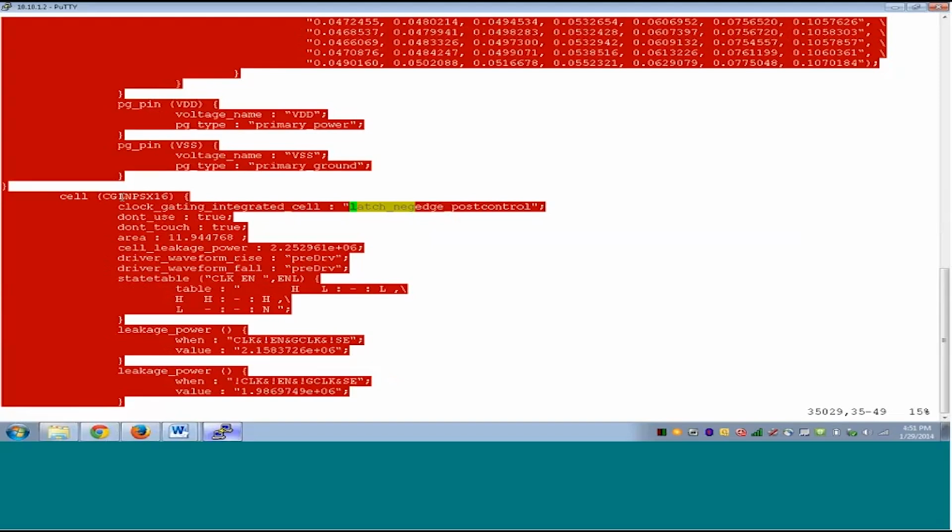Why? Consider a 16-bit shift register with feedback logic, a perfect circuit for inserting clock gating cells. DC will insert a clock gate, there will be one gate, but this one gate will be driving all the clock pins of the 16 registers of the shift register. So the fan-out would be 16. Now consider what if there are 32 registers in the shift register bank. Again the fan-out will be 32.